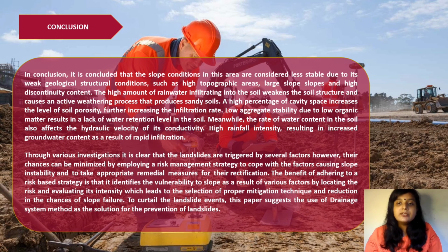A high percentage of cavity space increases the level of soil porosity, further increasing the infiltration rate. Low aggregate stability due to low organic matter results in a lack of water retention in the soil. Meanwhile, the water content in the soil also affects its hydraulic conductivity. High rainfall intensity results in increased groundwater content as a result of rapid infiltration.